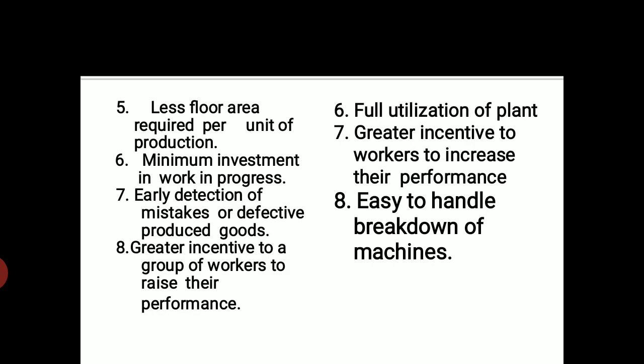What is important in product layout? Product plays a very important role, and the word sequence you have to remember. In process layout, the function plays a very important role, the process plays a very important role. What is the speciality of this type of layout? Similar functioning machines are kept together. The third one is static layout or fixed layout, in which the product does not move.